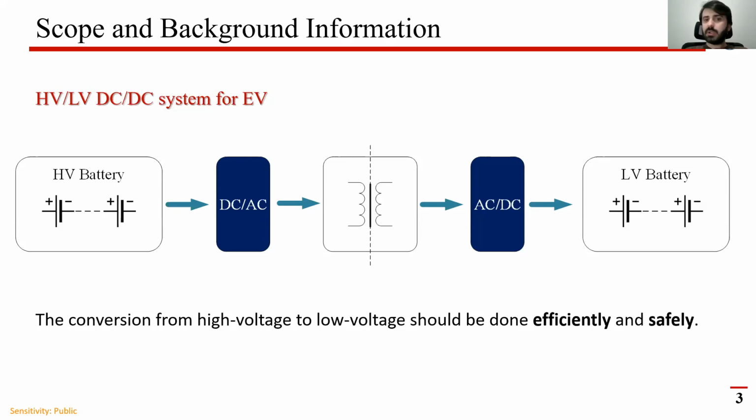Actually, isolation is the best choice, I think, in this application, because LM is the transformer component, but also it provides resonance in some conditions. Also, maybe we don't change the duty ratio, but we can adjust the output power just by changing the frequency.